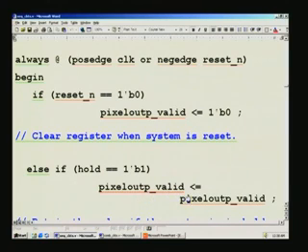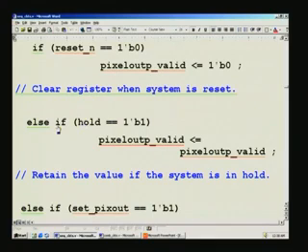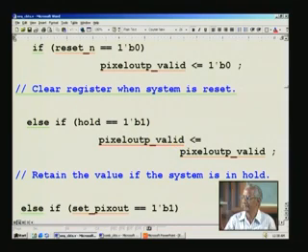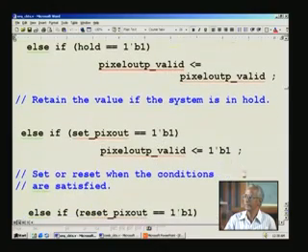And the same thing, if there is a hold like a microprocessor signal, it will just write back itself, and that means to say it does nothing but just idles. So long as the hold is asserted, it keeps on going in this block, looping here. That is how it preserves at the time of hold, and when hold is removed, it continues from where it left, it does not start from square one again. That is the beauty of using a hold.